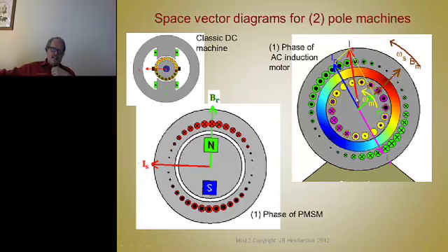See, this is not 90 degrees. But normally it's 90 degrees. In synchronous machines, the current is 90 degrees to the B field, but in an induction motor it's a little less because of the slip. And the only way to get slip is to load this thing down, so you slow the rotor down so the rotor is going slower than the stator field, and the difference between those two is called the percentage difference, called the slip.